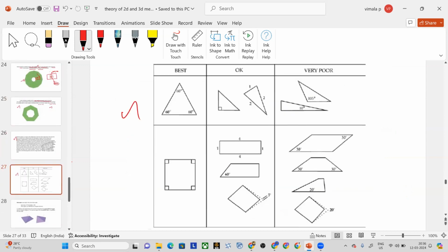So you have basically, for 2D mesh, two types of elements. One is triangular and another one is quad, right? The best triangular element we actually require from meshing is the equilateral triangle. In an equilateral triangle, all three sides are equal, and the included angle between the sides should be 60-degree, right? This is the most preferred. A right angle triangle is also fine. But this kind of triangles are very poor.